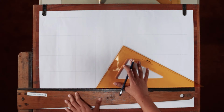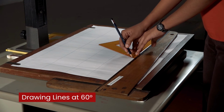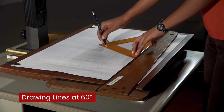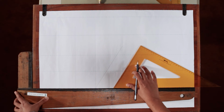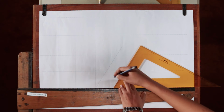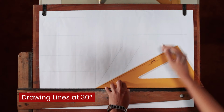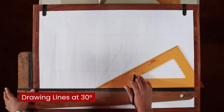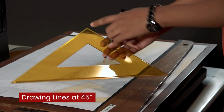Observe how the set square is placed to draw a line at 60 degrees joining one of the horizontal lines. Make sure that the set square is also held firmly, preventing it from moving when the line is being drawn. This is how you draw a line at 30 degrees. Use the same technique to draw lines at 45 degrees.